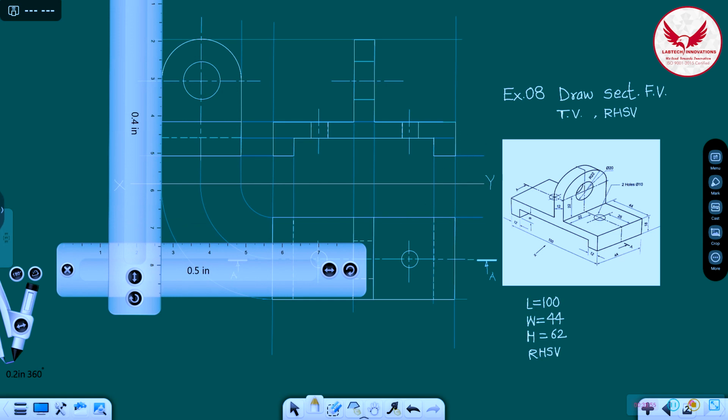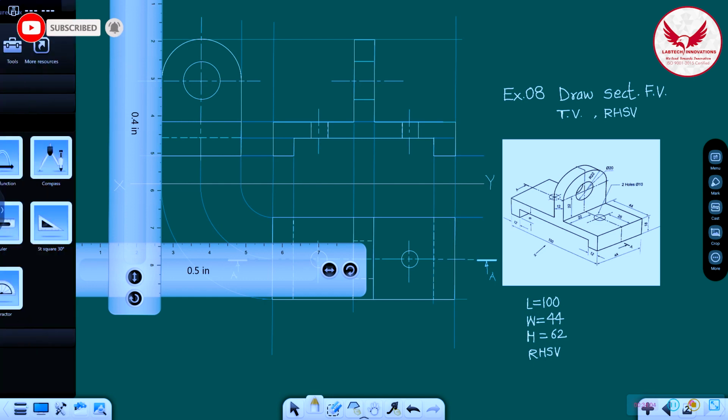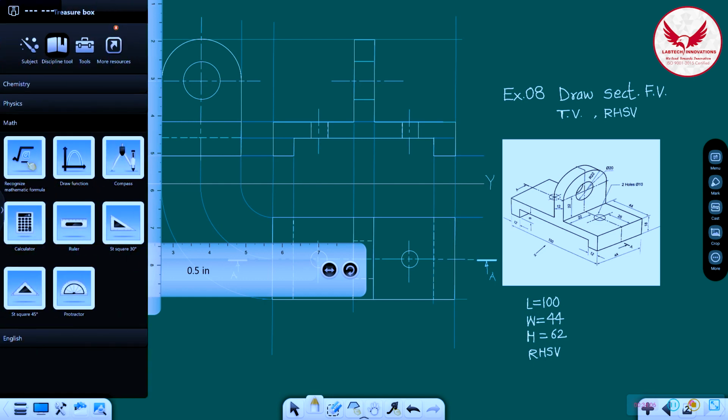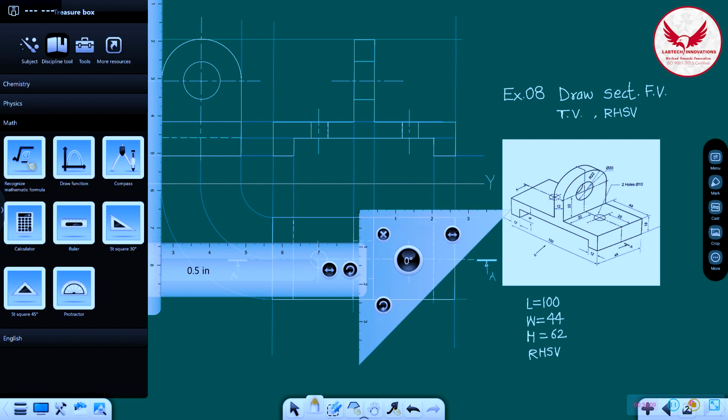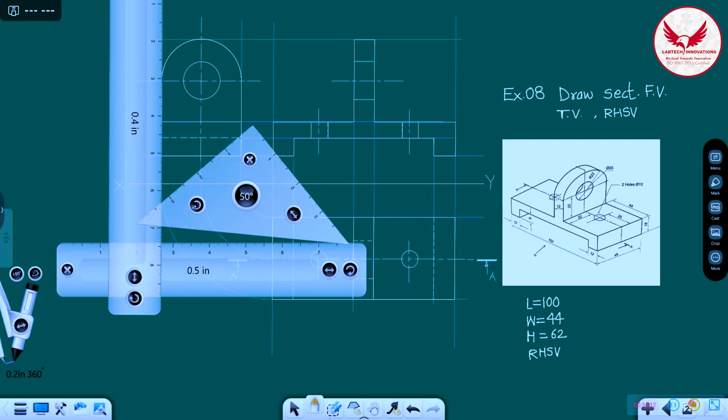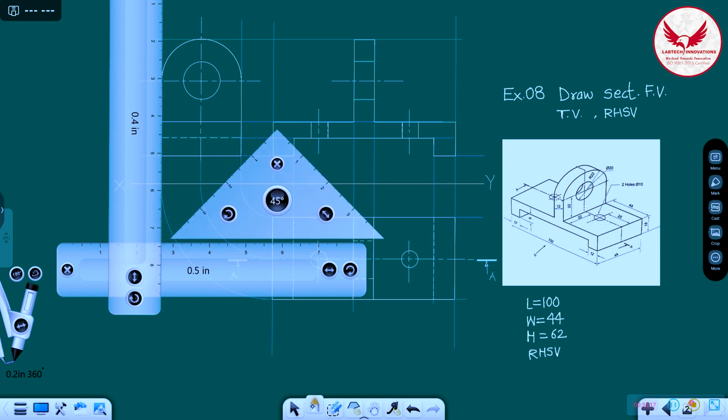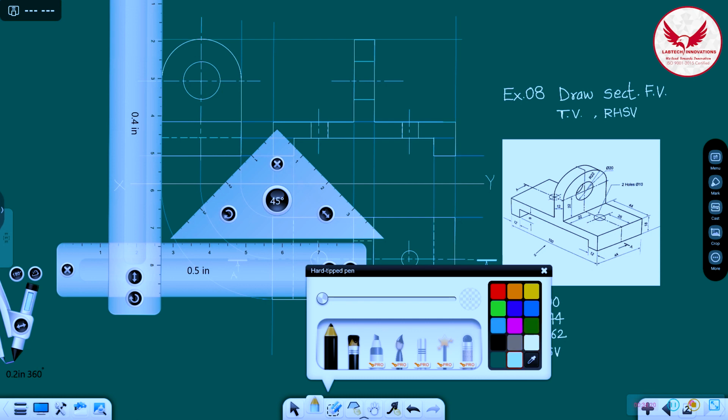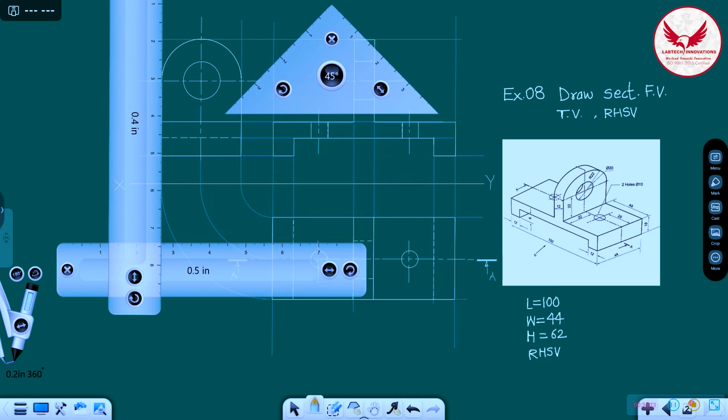And on the newly cut shiny surface, we have to show the hatching lines. Except these three holes, everywhere we'll get the hatching lines, and for that hatching line, use 45-degree lines. And how can we mark these hatching lines? We can mark these hatching lines like this, a little bit lighter than the object line.